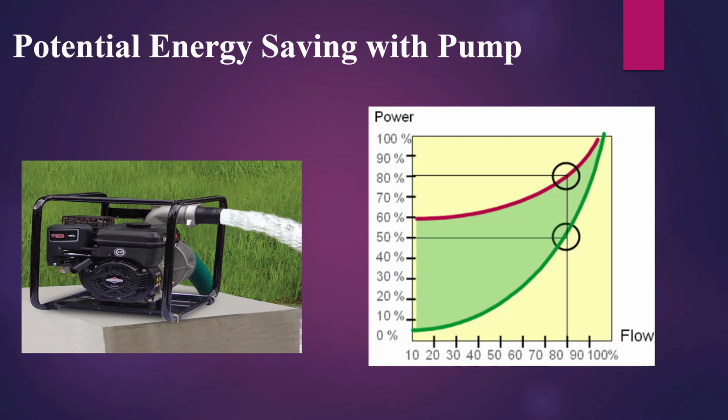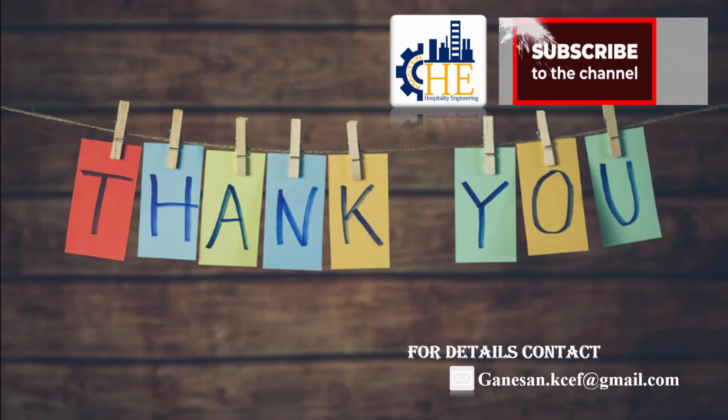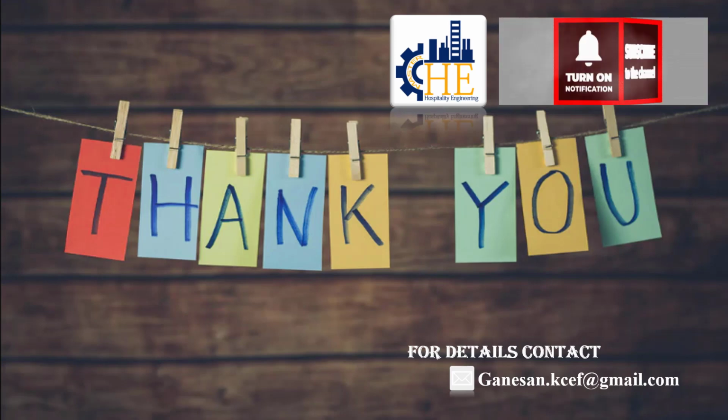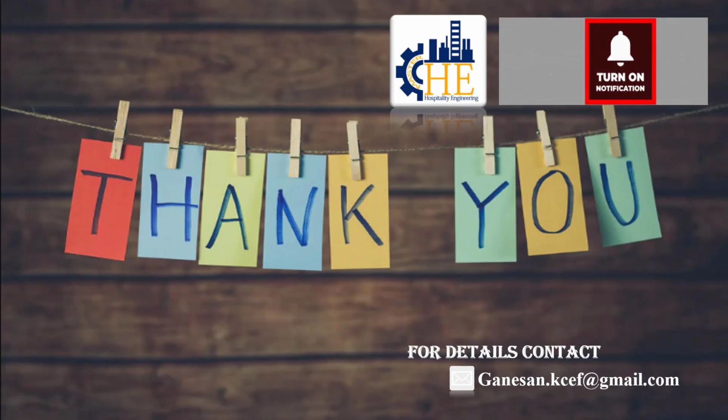Providing 80% of the flow, the pump only consumes 50% of the power rather than 80%. Providing 50% of the flow, the pump only consumes 20% of the power rather than 65%. In this video, we have demonstrated energy efficiency using speed control, which will have one more part to conclude it.